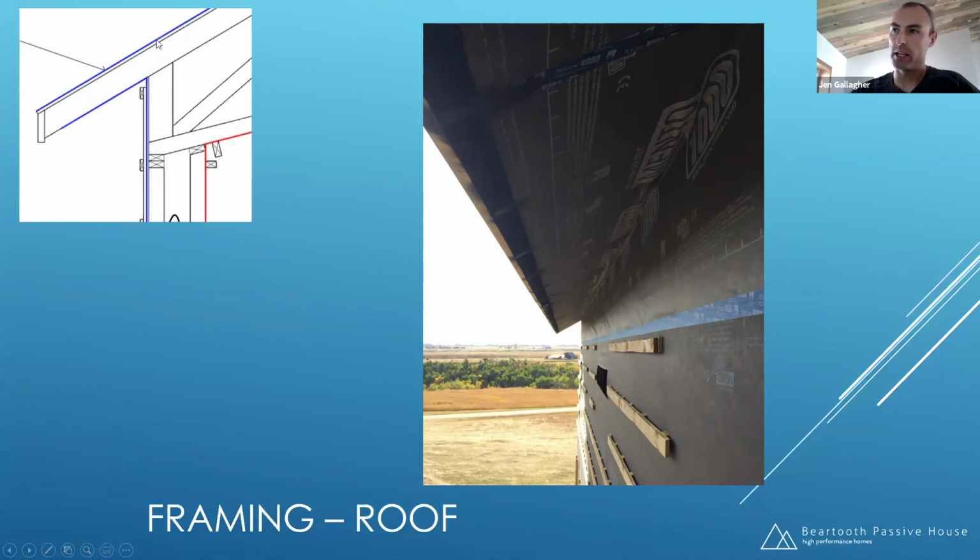So that warm air would be hitting the underside of this sheathing right here, which could cause some ice dams that you see in a lot of older homes. But they're there because there's no insulation right here, and the air tightness is really bad. So you get a lot of hot air from inside going up and warming that up. So what we ended up doing is wrapping that WRB on the underside of the eaves as far as we possibly could.